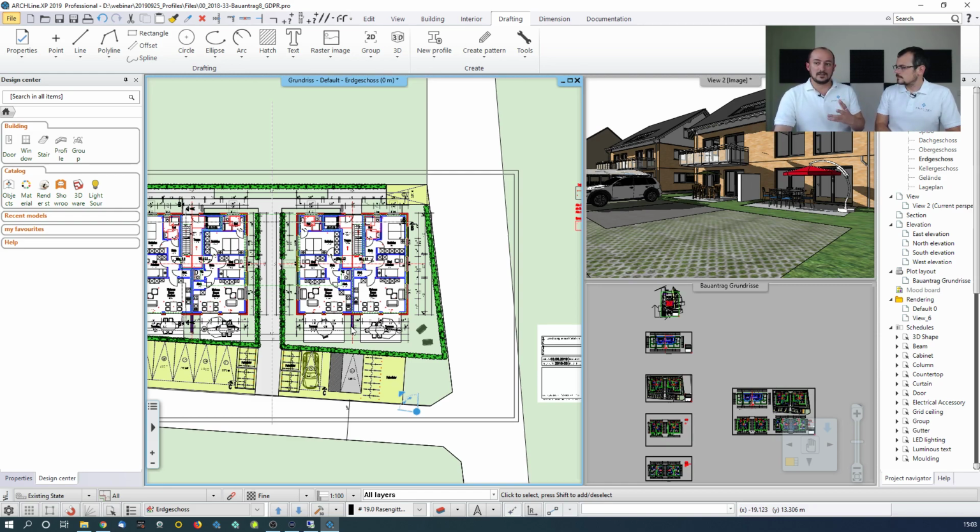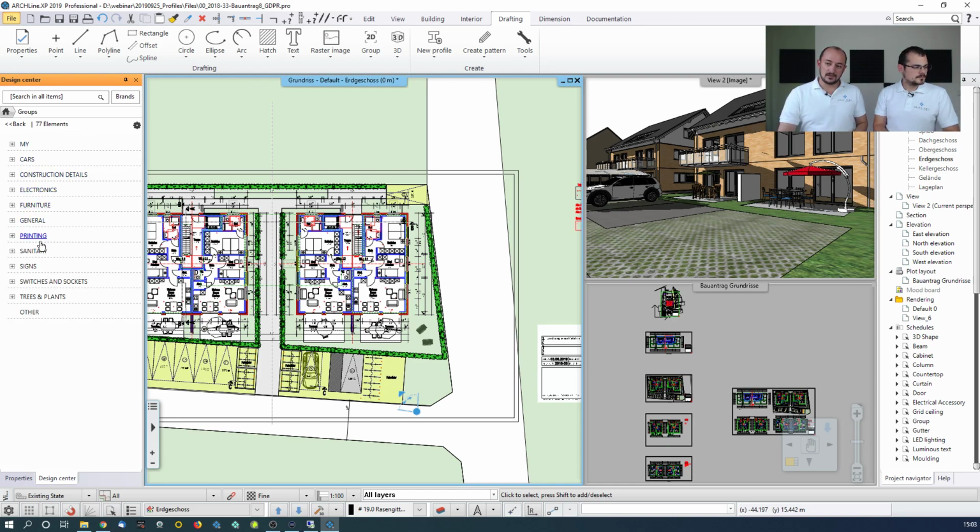Now it's important to talk about these as 2D representations of items. You can find them in the Design Center. In the Design Center there is a specific dedicated button for the groups, which brings up the library of the built-in groups, and this is also where you will find your own groups, that what you create and what we will actually create today with these tools.